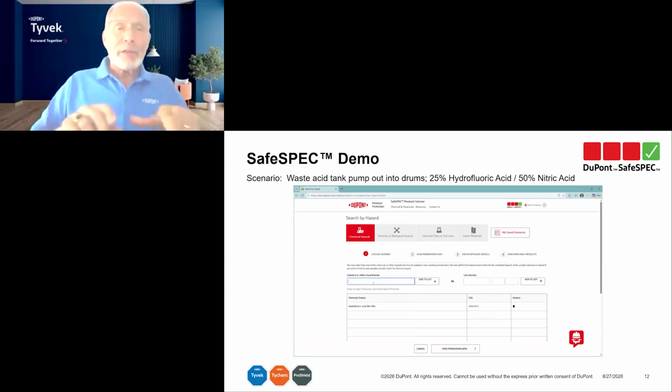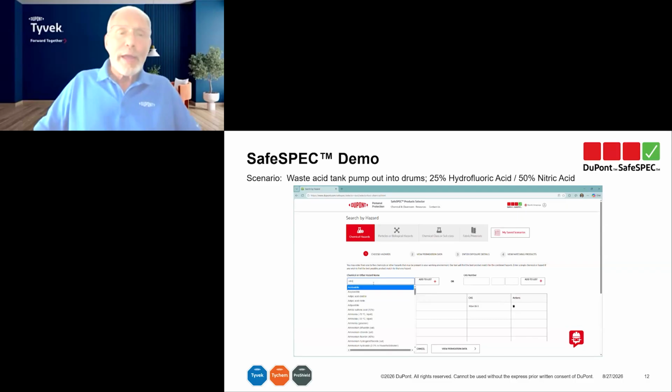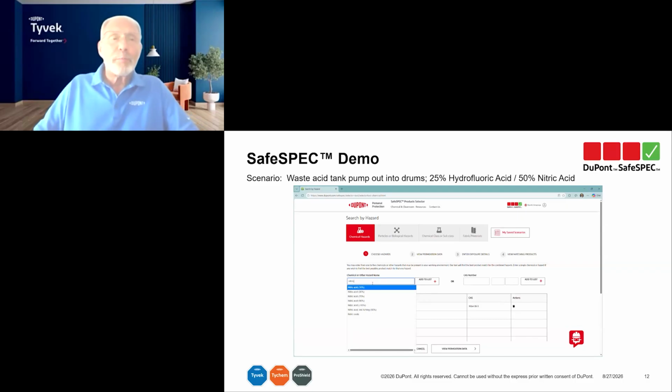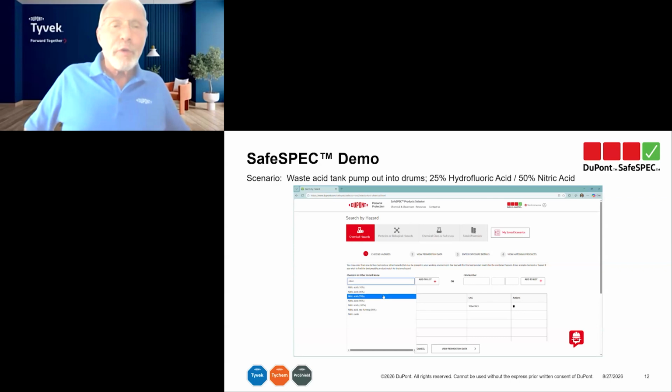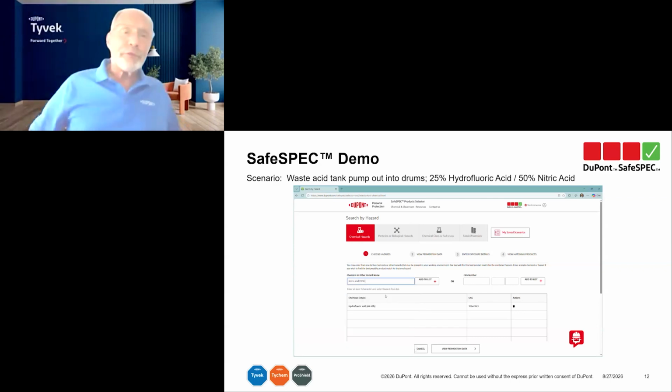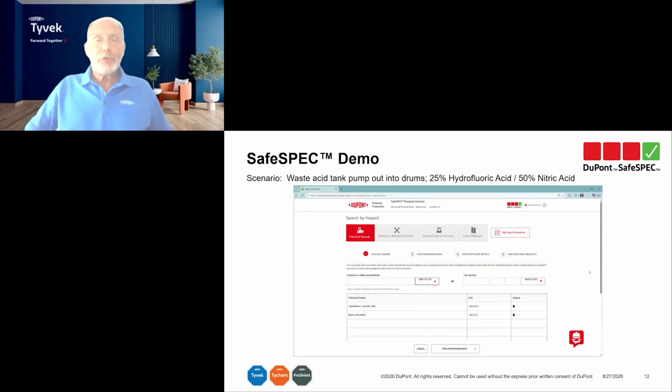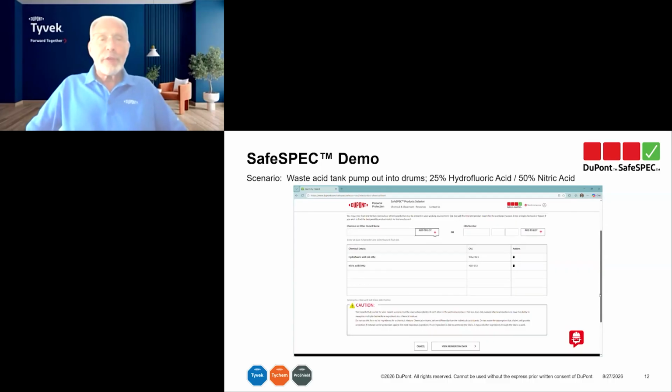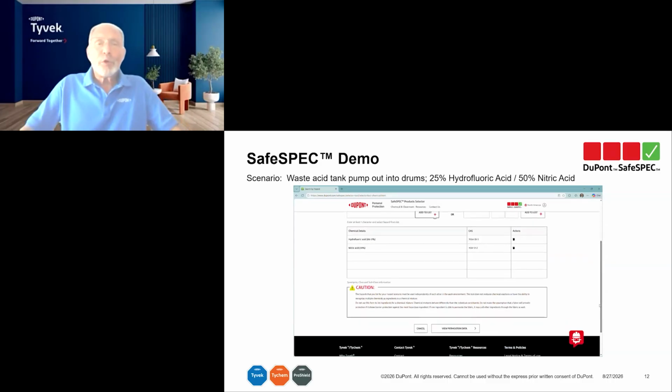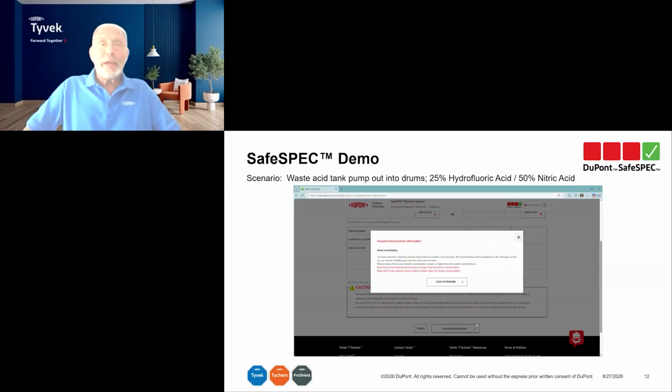So again, based on concentration, we're going to select hydrofluoric acid 48 to 51%. Same thing for nitric acid. There is no 50%, so we have to go up. We're selecting 70%. So again, we have our two hazards identified. We're going to proceed to the next step, which is to review the permeation data.